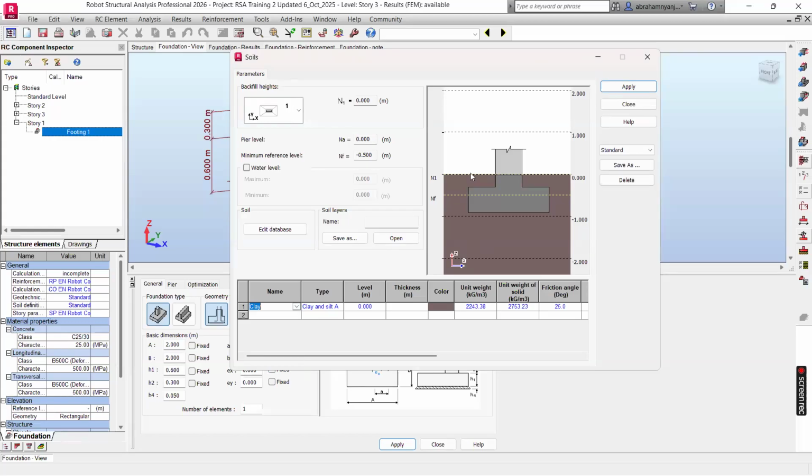For other critical structures, like bridges, designers do boreholes at whatever depth, 20, 50 meters, and the entire soil profile will be highlighted very well: on top you have a soil of this bearing capacity, this thick, then another soil type of this bearing capacity and angle of friction, then at 20 or 30 meters you have bedrock.